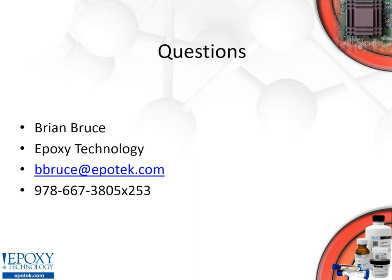So designing that into your process flow will give you a massive benefit in terms of the actual thermal management within part. That just needs to be taken into consideration in terms of how you're expected to do your cure schedule, because stepped cures will take a longer amount of time, but it will give you a better result overall.